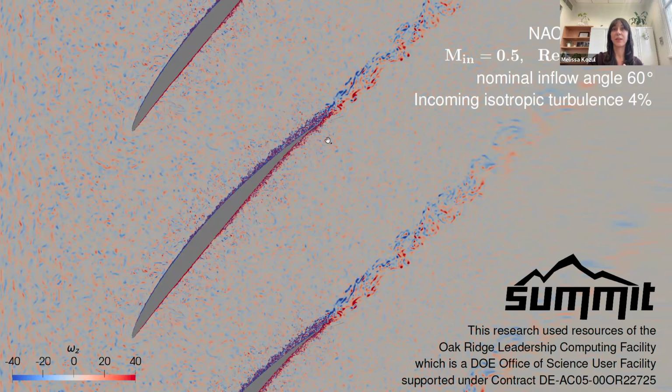The Reynolds number in fluid mechanics is the separation of scales, basically the ratio of the larger scales in the flow to the smaller scales in the flow. This increases with fluid velocity. It also increases with scale. So you have much larger Reynolds numbers, for example, on the outside of a plane fuselage than you do inside the engine. But this is an important thing that tends to increase the cost of our numerical simulations. That's why we cite it. But it's important to match this to have the same fluid flow behavior as the engine.